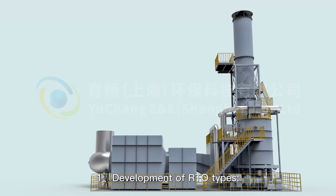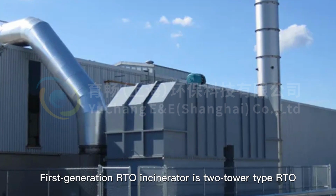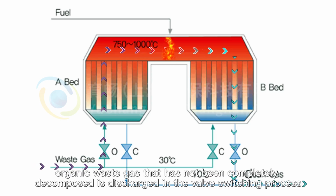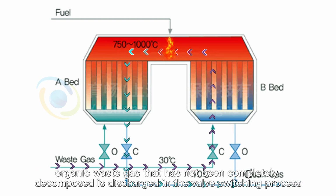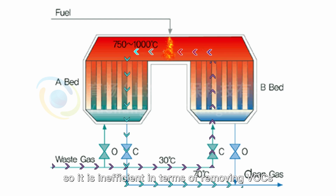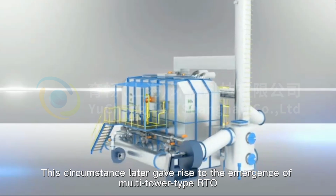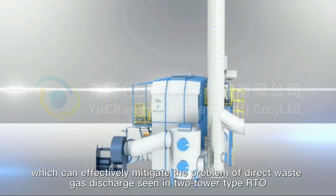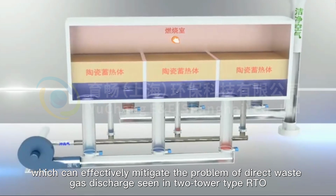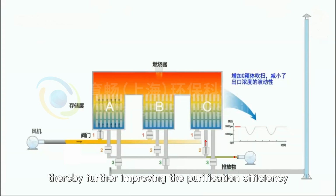Development of RTO types. First generation RTO incinerator is 2-tower type RTO, and with such configuration, organic waste gas that has not been completely decomposed is discharged in the valve switching process. So it is inefficient in terms of removing VOCs. This circumstance later gave rise to the emergence of Multi-Tower type RTO, which can effectively mitigate the problem of direct waste gas discharge seen in the 2-tower type RTO, thereby further improving the purification efficiency.